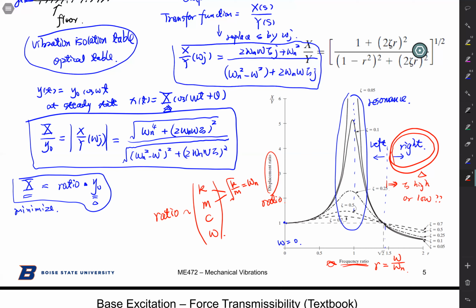So if you look at the curve, it should be low damping, right? Because when zeta equals 0.7, it's actually above the curve when zeta equals 0.1. That's actually against our intuition. When you want to isolate a vibration, my intuition told me that you might want to increase the damping so it absorbs more energy. But actually, that's not the case. In most vibration tables, you don't see a lot of damping.